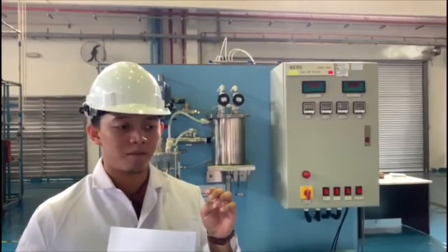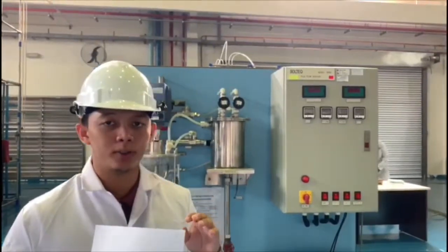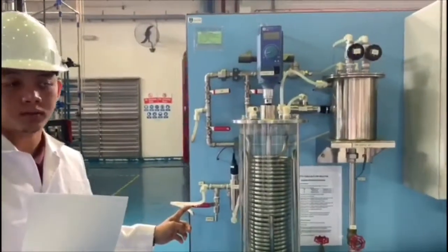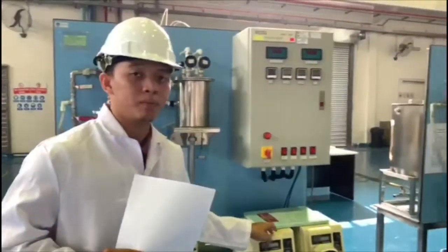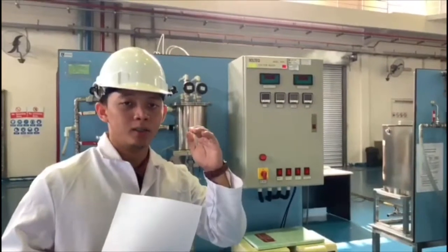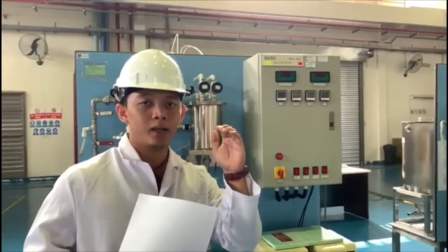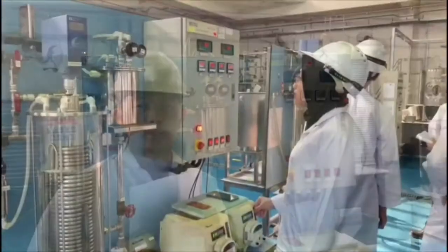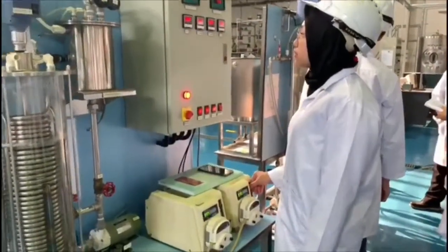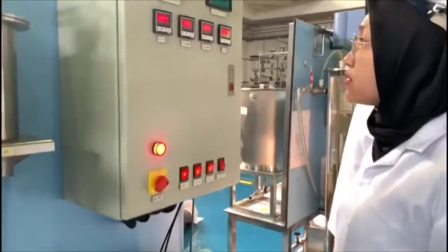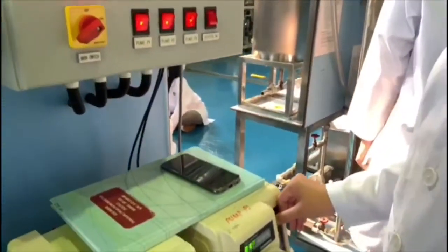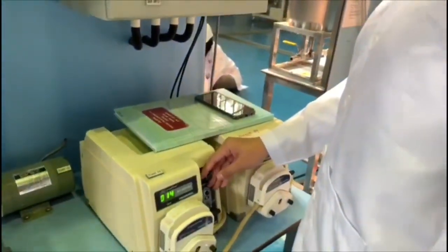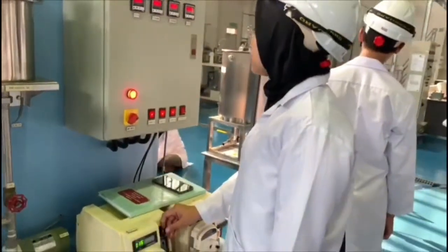First, perform the general startup procedure as mentioned before. Second, open valves V9 and V11. Third, allow both the NaOH and ethyl acetate solutions to enter the plug reactor R1 and empty into the waste tank B3. Fourth, adjust P1 and P2 to give a constant flow rate of about 300 ml per minute at flow meters F1-01 and F1-02. Make sure that both flow rates are the same.